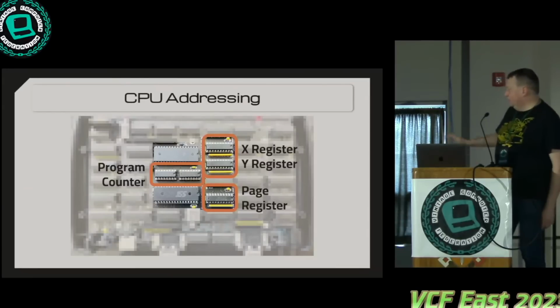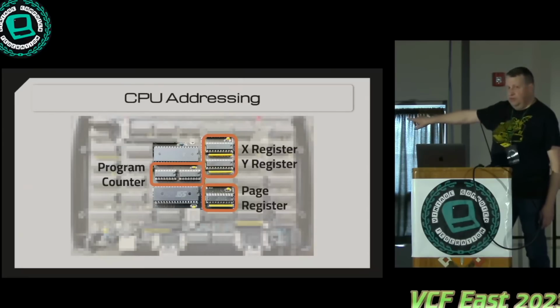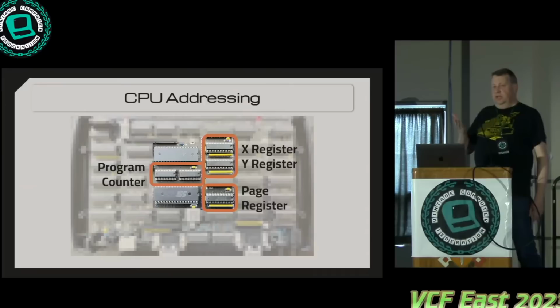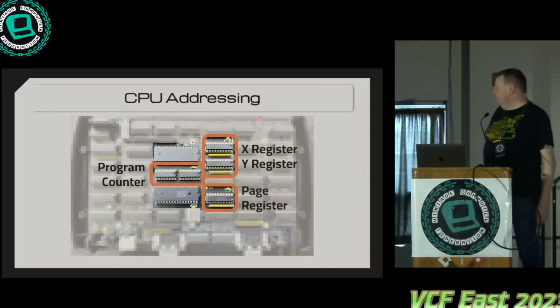And that's where all those chips live on the board. So there's the two memories, those are the two program counters, 4 bits. And then there's a page register, and then the XY register. You might notice there's these resistor networks. They pull high, so you can actually default any of these addresses to FF just by not turning them on.